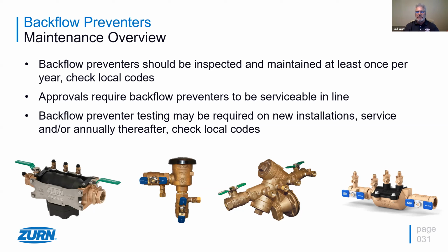And then some areas of the country require backflow testing on all backflow preventers in any one given area. A perfect example is the city of Indianapolis. They actually have a backflow testing code throughout the entire city on all pressure vacuum breakers, and they have to be tested every year. You get out into some areas of Virginia or even down into Florida, and you test it when you install it, and then you walk away from it. And if it ever has problems again and needs service or maintenance or replacement, then you test it again. But until then, it could be years that go by that the backflow preventer has never been looked after.